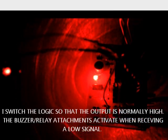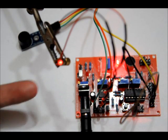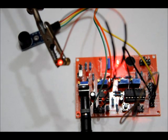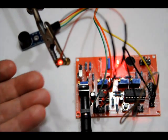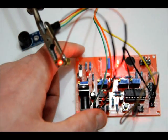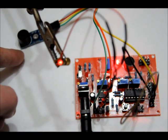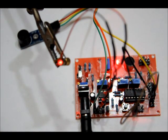So let's connect our buzzer attachment. I've switched the comparator wires again so that the output is normally high. The LED would be on right now with the laser or light hitting the sensor. As soon as we bring darkness into the equation, it won't work right now because there's too much light in the room, but as soon as the output is brought low, the buzzer unit, which we've connected again to the CP1A output of the comparator, will emit an alarm.